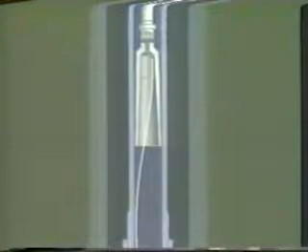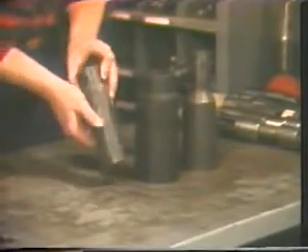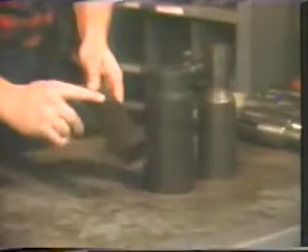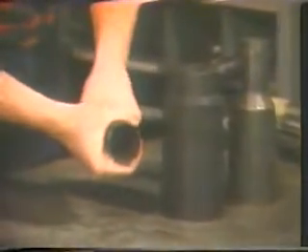One type of wire finder is a soft metal cylinder which can be flared out to conform to the ID of the tubing in the well at the time. When lowered on a conventional wireline tool string, the wire finder will contact the top end of the wire line, and the specialist can coil or ball up the broken end of the wire, allowing it to be engaged much more easily with a wire grab. Another type of wire finder uses a metal skirt, which is slotted to allow it to flex out against the tubing wall. The slotted cylinder will allow the wire finder to be run through reduced ID restrictions in the tubing and flex back out after passing the restriction.